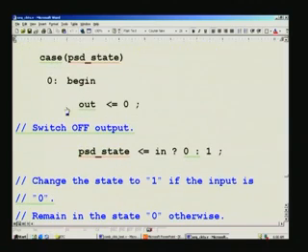So, that is in case 0. We are having a decimal number instead of name S0, S1 etc., and output needs to be 0, that is what we have seen, and once again we use a mux for this state for determining the next state as such. It all depends upon the input. If it is 1, we need to remain in the same state, that is what we have seen in the figure, and otherwise we wish to go to the S1 state.